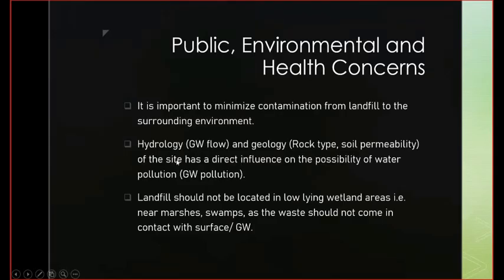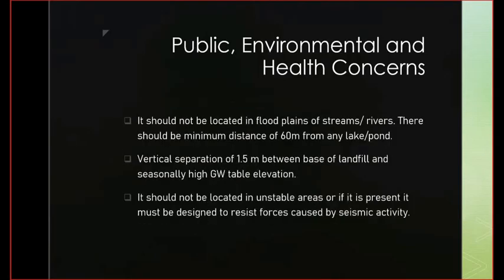Hydrology and geology of the site has a direct influence on the possibility of water pollution in landfills, so we have to be careful about that. Landfills should not be located in low-lying wetland areas like marshes, swamps, as the wastewater should not come in contact with the groundwater. It's a major concern that we have to stop pollution of groundwater in landfill sites.